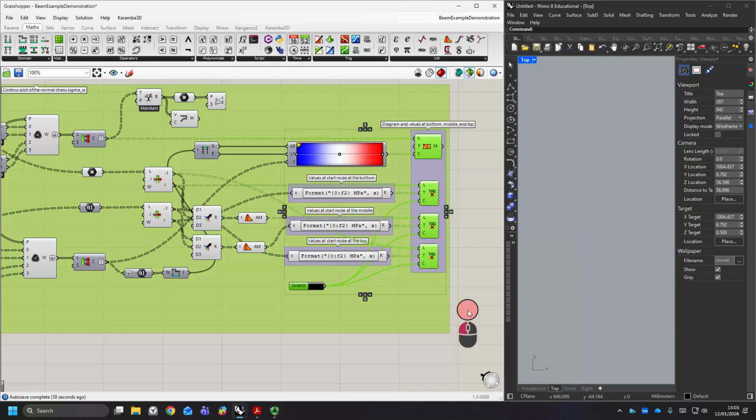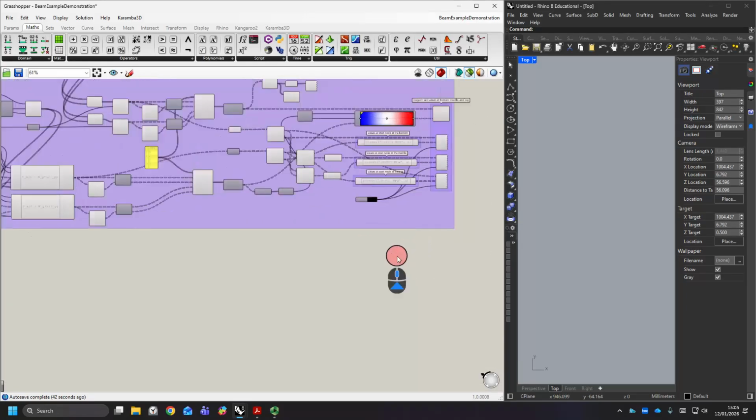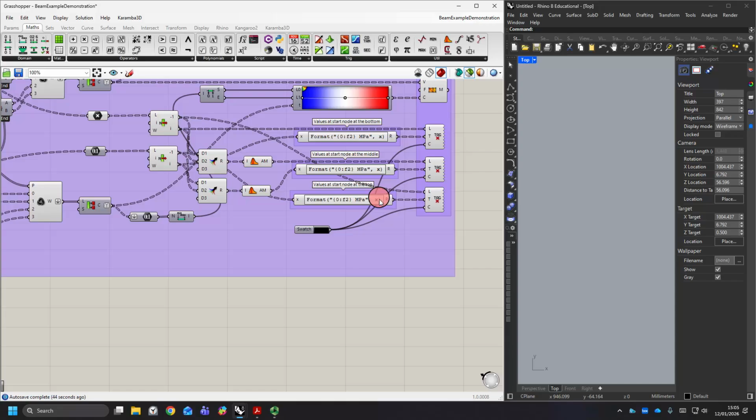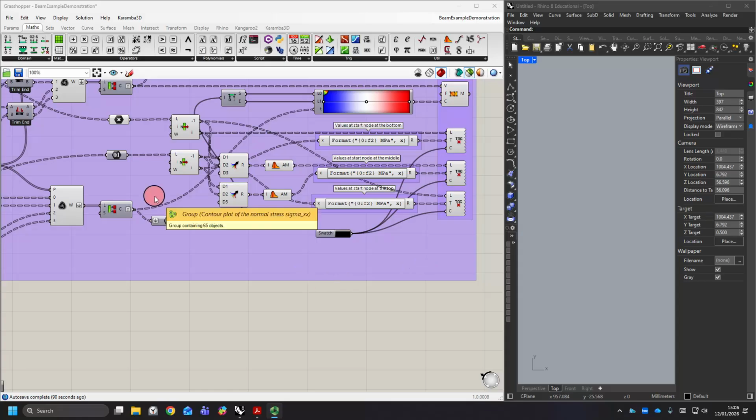So the very final thing we can do is a little bit of processing of the values in order to get out what we're going to call the abs max stress. Obviously we're doing all of this to see whether material is likely to yield or not in the structures that we're analysing. So that's why it's of interest to find the abs max stress, to see if it exceeds a yield stress value.